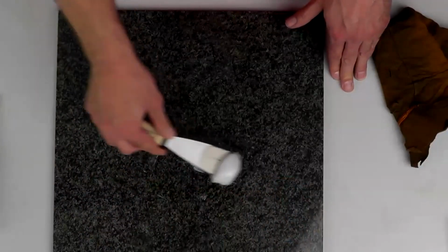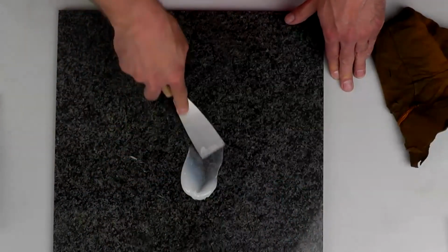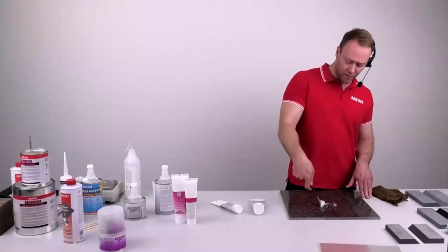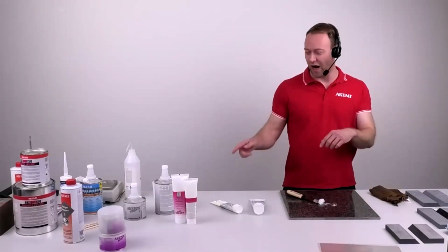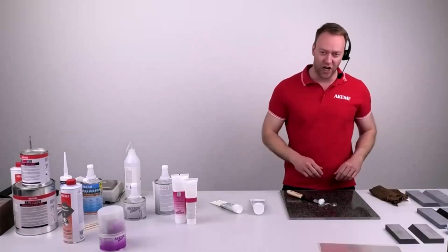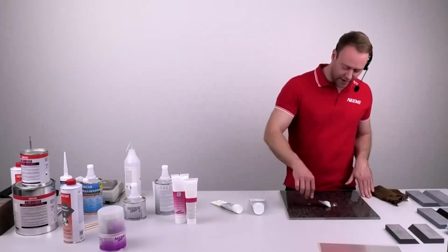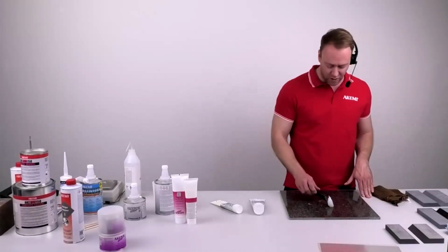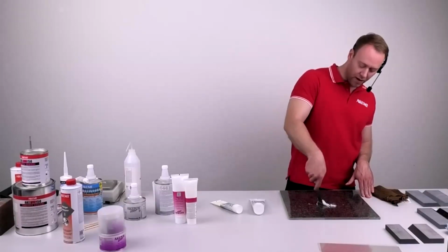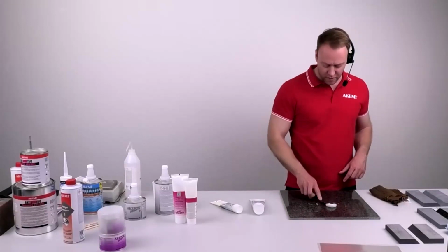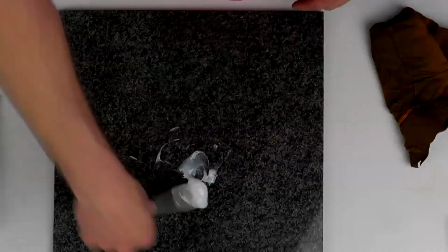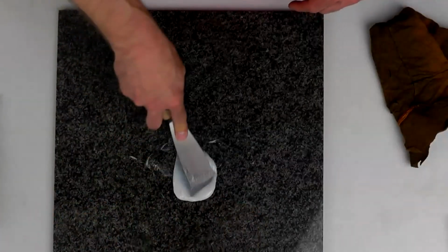With polyesters, it's a little bit easier because it's a polymerization. When it gets knocked with the hardener, it starts a chain reaction and gets cured. But still, to get a proper, let's say, homogeneous curing, also here use 30 seconds to 1 minute to mix your mixture properly.